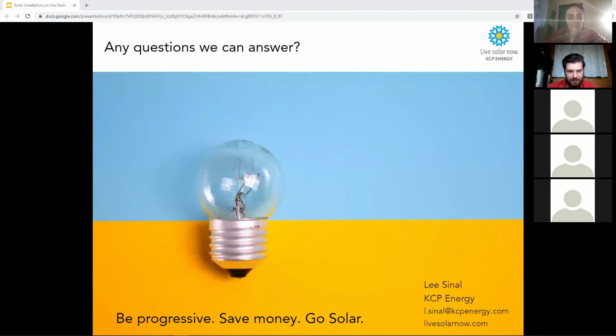So the one question I have here is, how long do the solar panels last? Maintenance cost, life of system. So the panels have kind of a dual warranty on them. They have a manufacturer's guarantee that the panels will be free of defects for anywhere from 10 to 12 years, which is pretty common. And then they also have a system production warranty, and that's a 25-year warranty. Essentially what it guarantees is that by year 25, the panels will still output 85% as much as they did on their first day of operation.